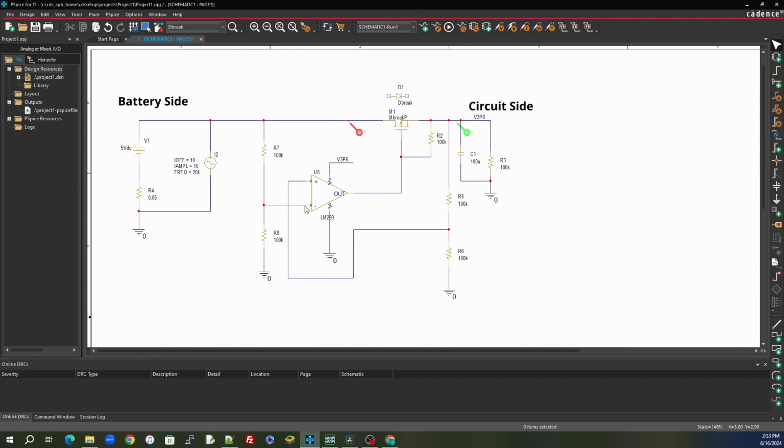So what's going to happen is my N minus is going to at some point be less than my N plus. As soon as my N plus is greater than my N minus, then no longer will the output be connected to ground, but it'll go high impedance. When it goes high impedance, it'll turn this MOSFET off. As soon as that MOSFET is off, then what's going to happen? Well, that means that this voltage is less than this voltage.